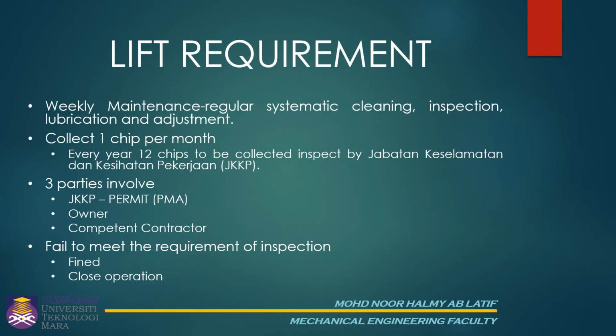Lift requirement. The lift must have weekly maintenance: regular systematic cleaning, inspection, lubrication and adjustment. Collect 1 chip per month, for every year 12 chips to be collected, inspected by Jabatan Keselamatan dan Kesihatan Pekerjaan (JKKP).